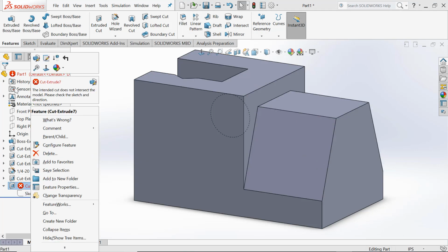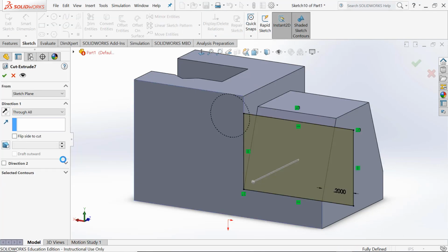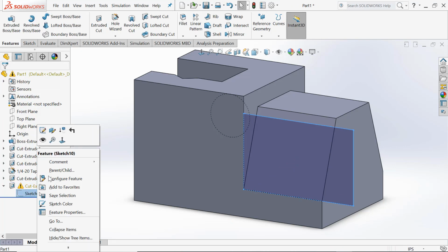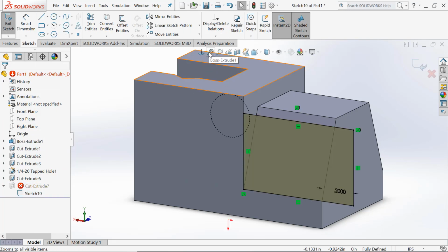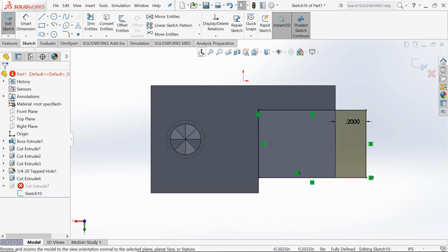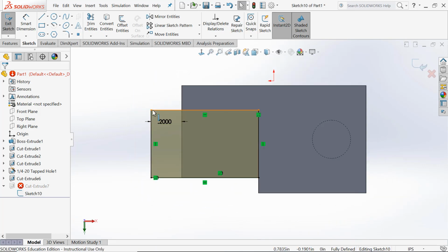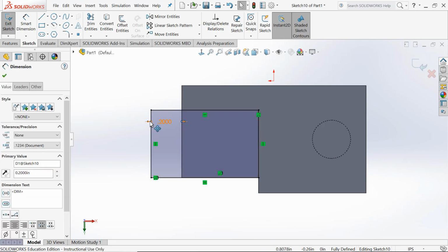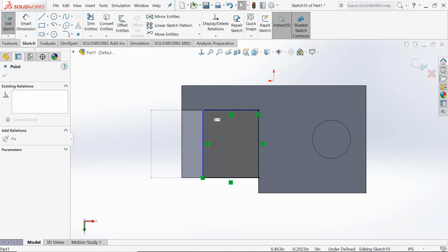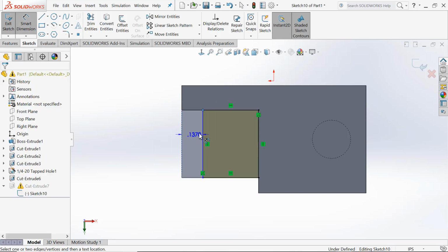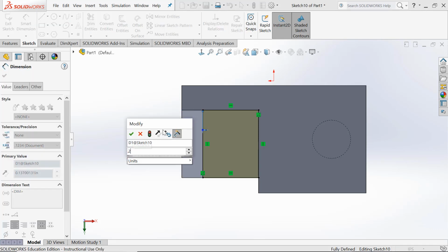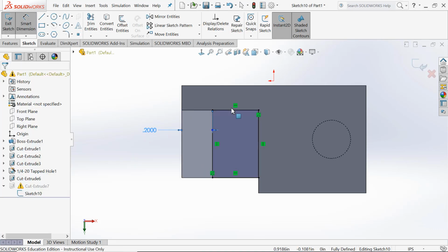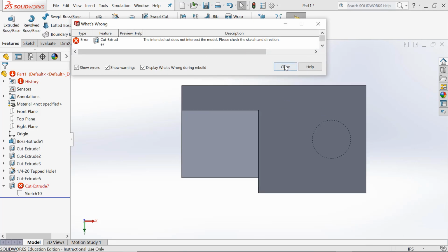Give me a little bit of an error here. Let's see what that was. I think I see what it is. This sketch is still in error. After I moved it, I made a mistake. Yeah, that point got flipped around to the wrong direction. If that happens to you, just delete the dimension, move it to where you do want it, and reinstall the dimension. So that's an interesting error to have right then, something I could totally see one of you students making and not realizing what was going on.